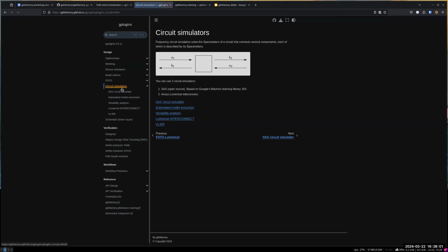For those who are not familiar with S parameters, in RF and photonics, your component can be described as an S matrix, like a matrix multiplication. So you have input fields and output fields. And for example, you have a matrix that tells you what's the relationship between the output field versus the input field. So for example, if I want to compute B1, I can get the S. So it will basically come from the multiplication of the input field by the reflection.